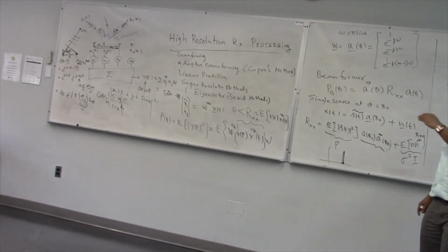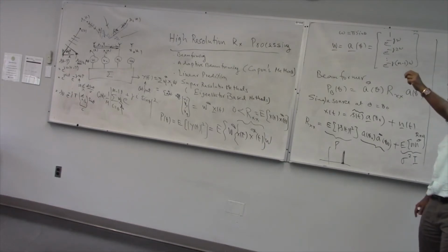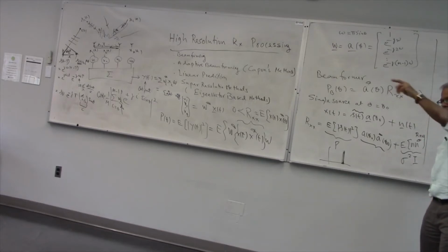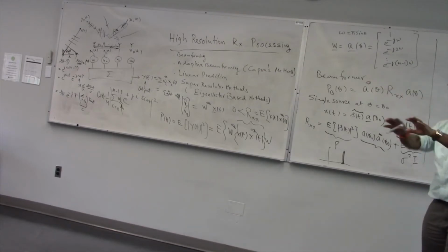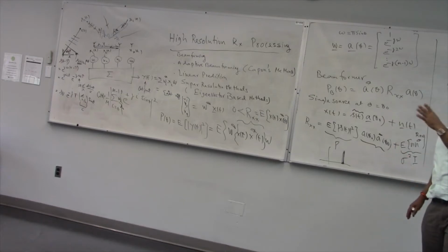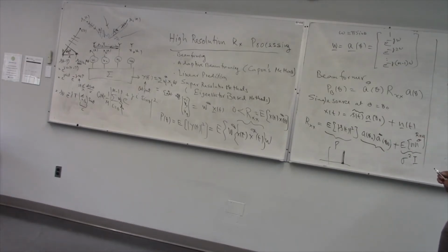Or remember what the phase shifting is doing: shifting it back to make the signals coherent. So if you know where it is coming from, you can compute the delay and shift it back and make it coherent also, physically. Like you assume a model, or you do hypothesis testing, saying assuming it is coming from there, then I know the path, so I know how much will be the delay. So just delay the received signal back, if that is the only signal, and if you do it for every conceivable location, at the right location, it will pop up. So that's called ray tracing in EM. We can do a similar idea here also, or you can go, so these are all signal processing techniques.